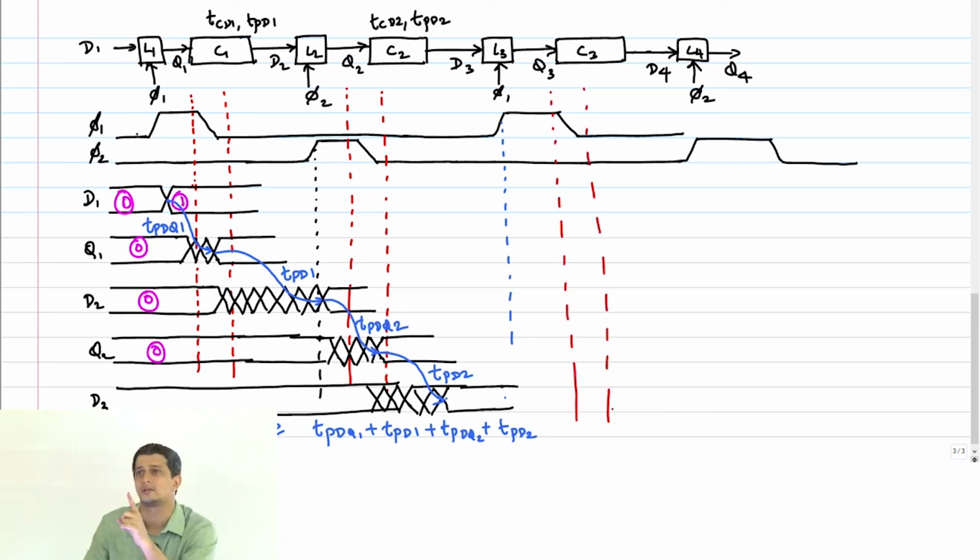As long as that happens, it will still function correctly, because that latch can sample it and hold it perfectly. No issue at all. But right now I don't want time borrowing from the neighboring cycle. What we are doing here, by allowing D2 to go into the level 1 of phi 2, is time borrowing from the half cycle, which is okay, which can be done under all conditions. We'll see an example where it is not possible, and where it is possible, then you will really understand. Okay. So now let's work under these constraints.